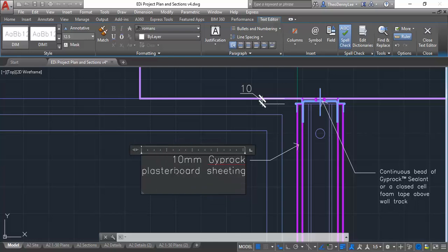Go to the viewport, double click or click on the paper button, and then just zoom to fit. Double click with the wheel, the middle button on your mouse. So on your layouts, you've got to make viewports.